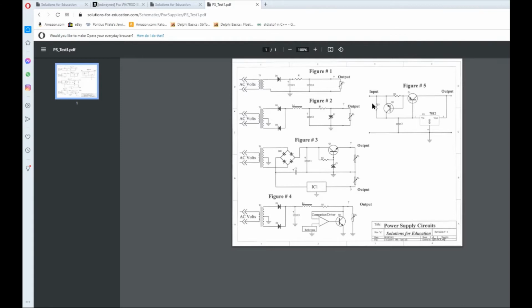The amount of current going through this resistor, this circuit is designed with certain values, and I'll point these out. The amount of current flowing through this guy here, let's say 600 milliamps, would be, look at where it is. This is the voltage between the emitter and, guess what, the base. Forget this transistor here for a moment. If this voltage gets to about half a volt and breaks over half a volt, going up to 0.6 of a volt, guess what? This transistor starts conducting because you have a bias voltage between the base and the emitter.